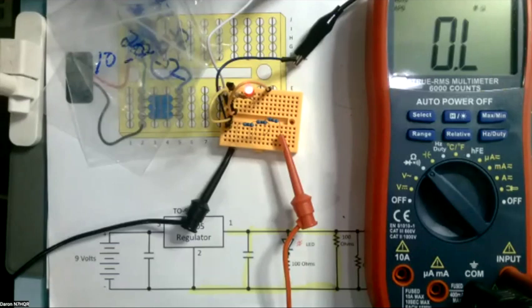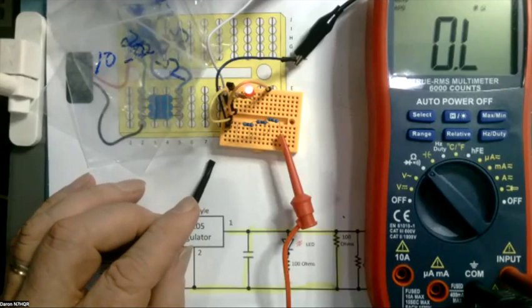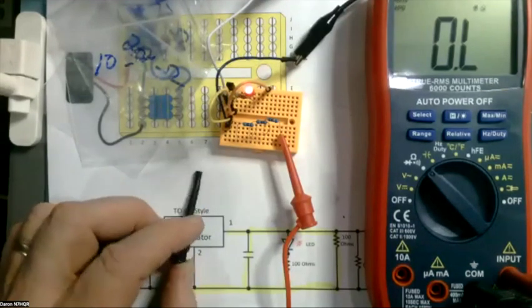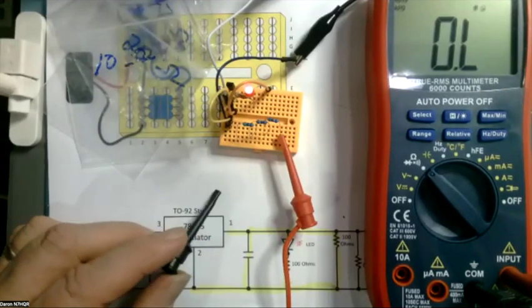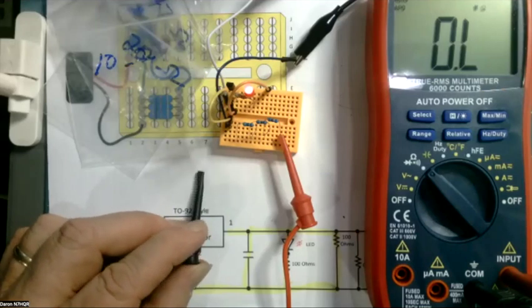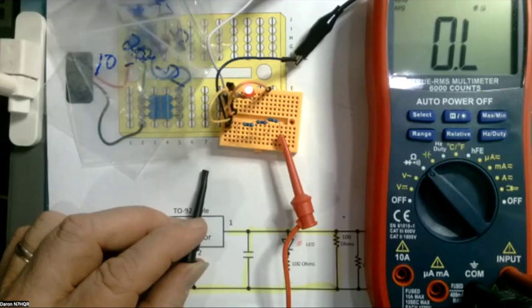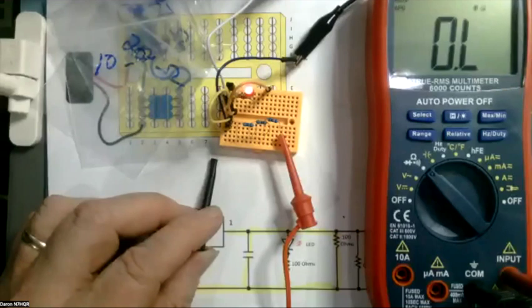77.689. Yeah, that's not unusual. You're talking about tenths of an ohm, just the amount of pressure you put on the probes. That's what I thought. So we're talking 47 ohm, 20 ohm, 10 ohm. So it should be 47, 20 and 10. It should be 77.